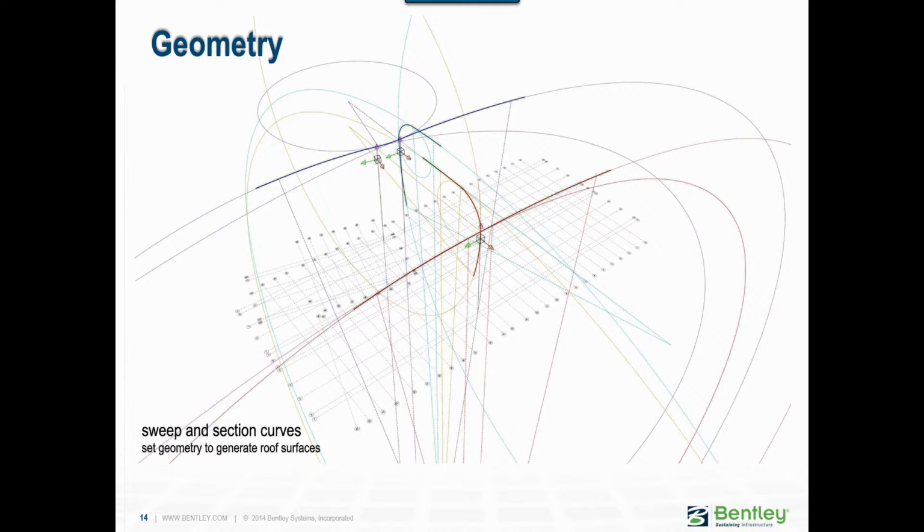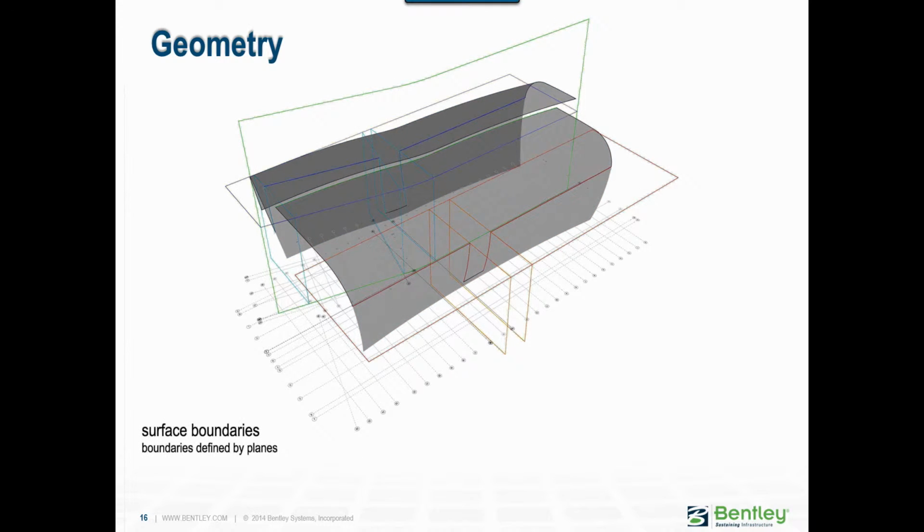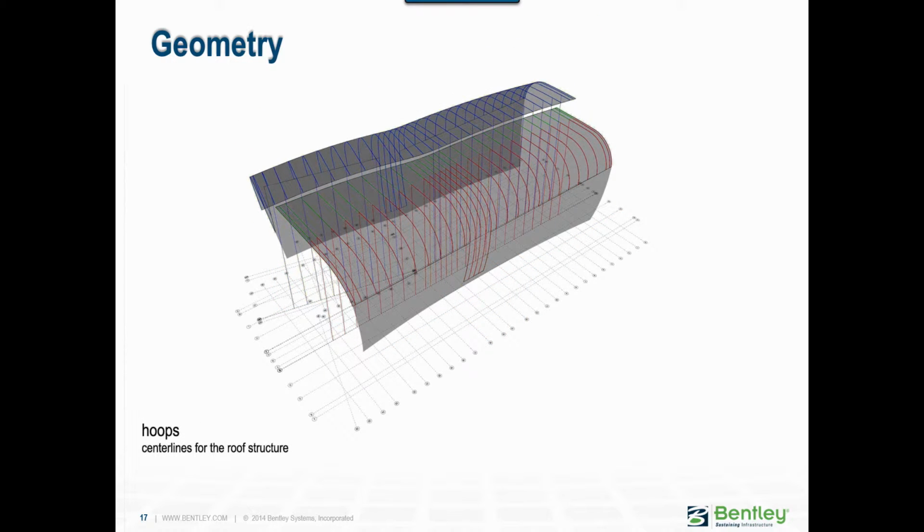The path curves of the sweep sections are concave in nature, resulting in a doubly curved roof for both section profiles. The intersection of the roof surface and planes results in the centerlines for roof structural members. And then again we divide the surface into parametric polygons which act as placeholders for photovoltaic panels or other customized roof panels.